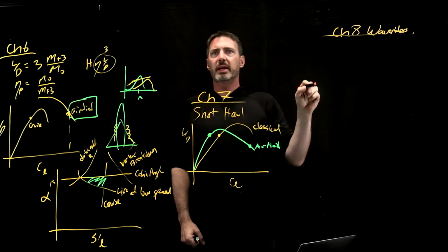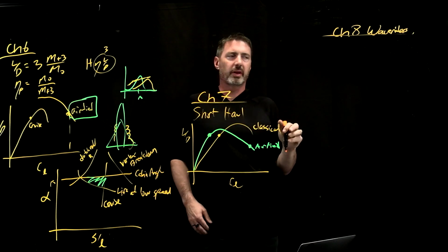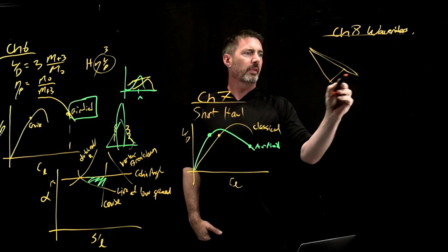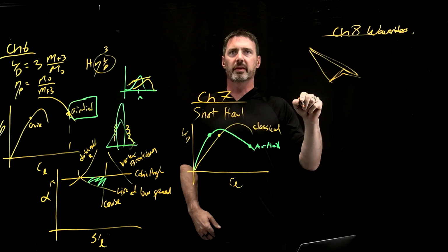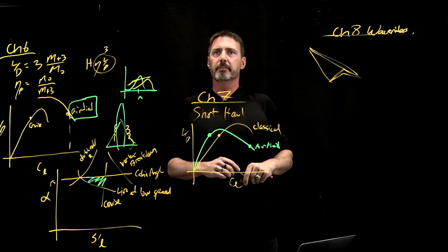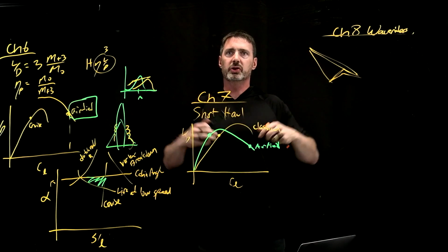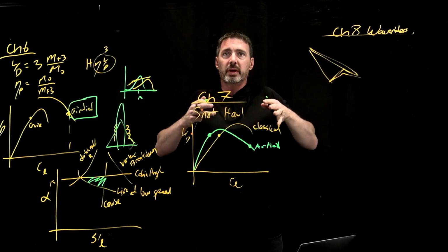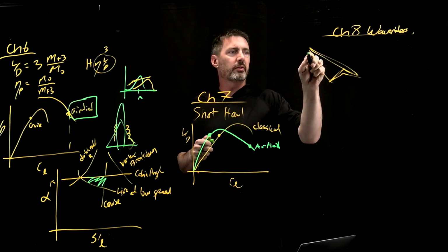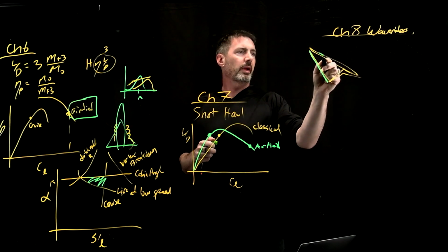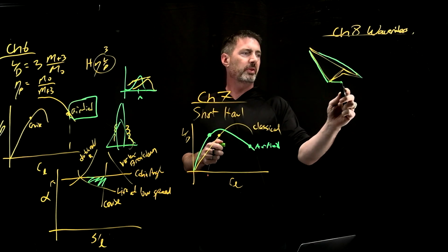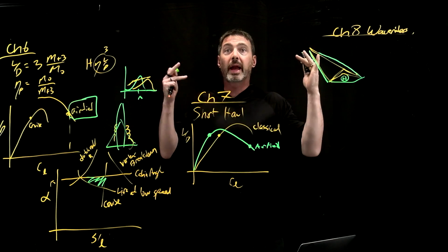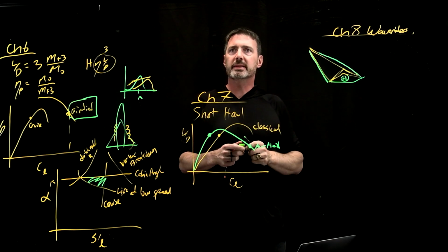And he does a pretty complete job of talking through the waverider, if this is the first time you've seen it. But ultimately, a waverider, and I'll try to draw the simple carrot version. Imagine I'm flying an inverted carrot like that. It's not a great vehicle. But as you fly faster and faster, the shock is getting closer and closer to the vehicle. At some point, it's actually worth having your vehicle reach out, if you will, and touch it from a design point of view, such that the shock is fully attached, right? And when the shock is fully attached, and the shock might be doing something different below here, you get a high pressure region below that the air can't escape around. So you get this increased lift.